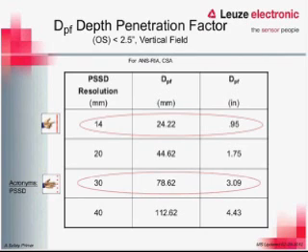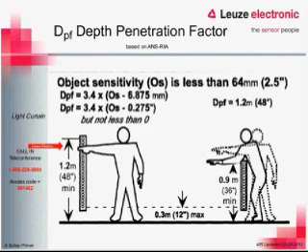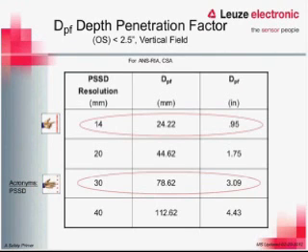So if it's 14 millimeter, we have to multiply that, if we go back here, by 6.875 millimeters or by 0.275 inches, depending on if you're in Canada or United States. And that gives us our depth of penetration in millimeters or inches. So at the smallest, which is a 14 millimeter resolution, finger safe, our depth of penetration is 0.95 inches or 24 millimeters. And that moves on up, obviously, proportionally, where we get larger resolutions.